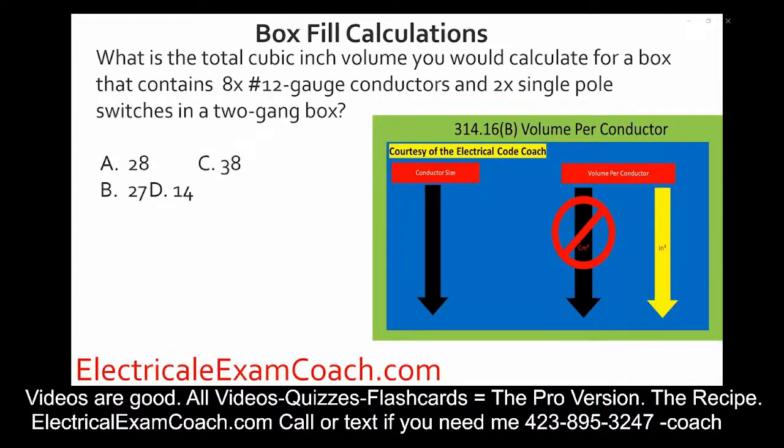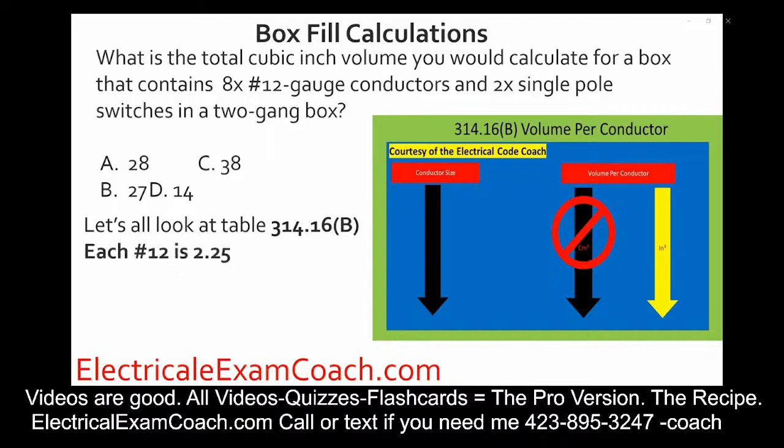What is the total cubic inch volume you would calculate for a box that contains 8 number 12 gauge conductors and 2 single pole switches in a 2-gang box? We look at 314.16(B). We know that each number 12 is 2.25. Let's go ahead and count our conductors.